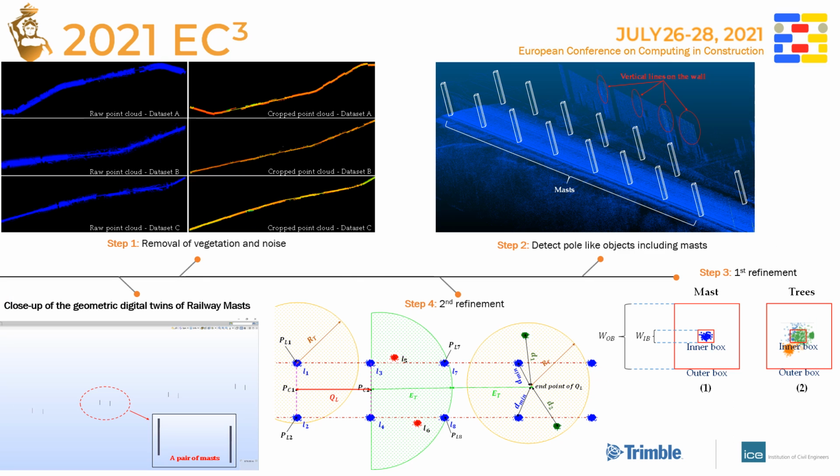A railway point cloud is usually given at an arbitrary position and orientation. So the idea is that prior to any subsequent steps, we first needed to align the pose of the railway parallel to global axes, because all features to be extracted in further steps lie in a global coordinate frame. To achieve this, we first align the rail track by chopping the whole dataset perpendicular to its principal direction.